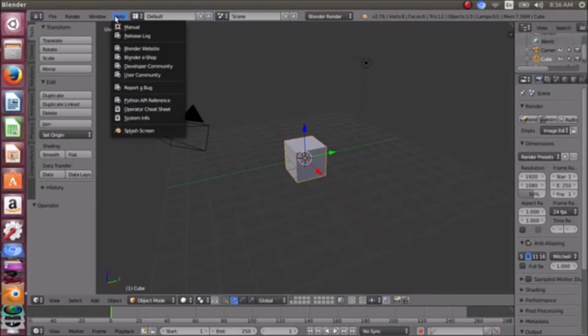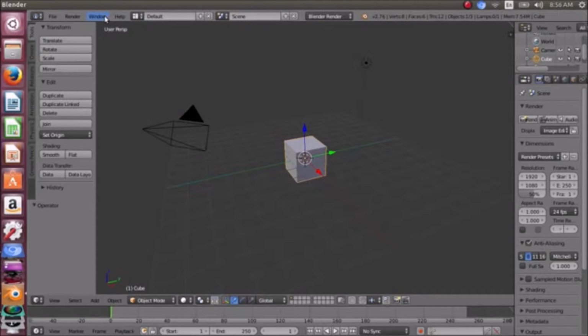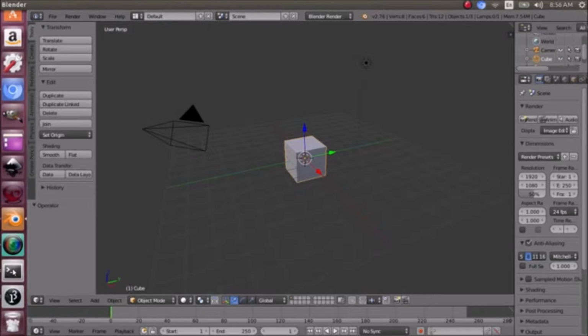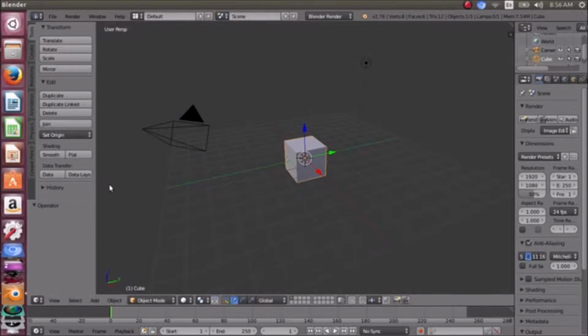If you're running in Windows, I believe there is, under either the Window menu up here or Help, an actual link that allows you to pull up a separate console window that'll give Blender data feedback. That will be important for the next script that I run, associated with the Bezier curve and Blender Python script, because that will actually read all the control point data that we need.